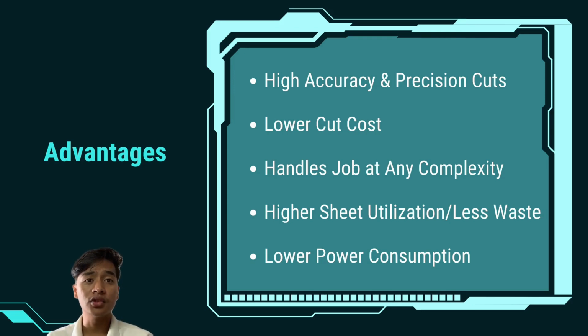Less time is required to switch out new sheets of material, and the machining and cutting processes squander less of your raw materials. Next, another advantage of the laser cutting process is lower power consumption. Contrary to presses and some other cutting tools which demand vast amounts of energy to deliver cutting force using a physical die, laser cutters have no other moving parts, even though the laser used to cut materials takes quite a bit of energy.